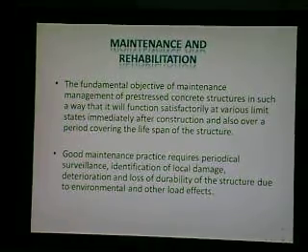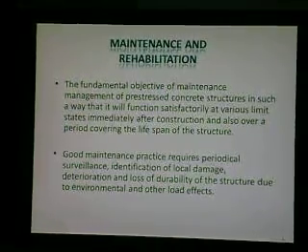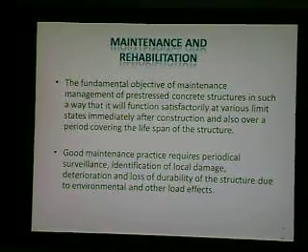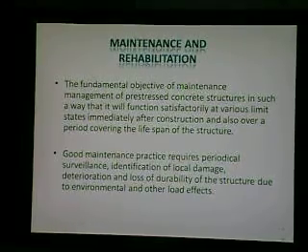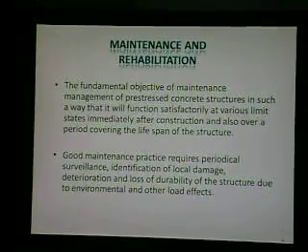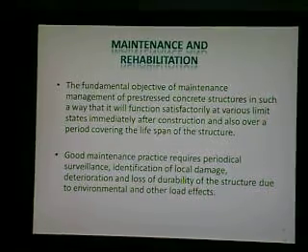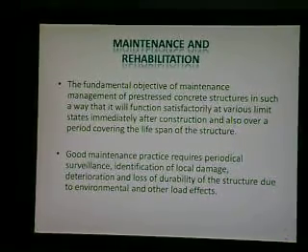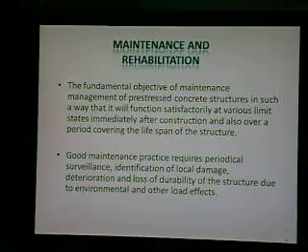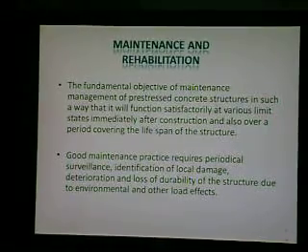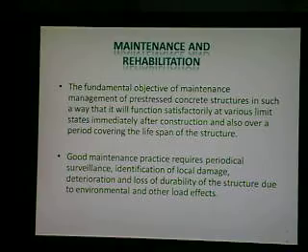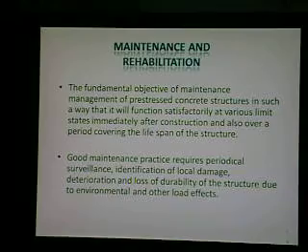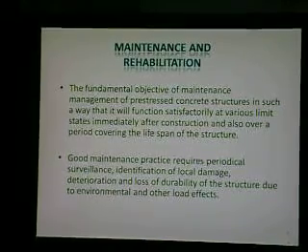Maintenance and rehabilitation. Just like post-tension slabs are an advanced technique, it requires maintenance and rehabilitation also. One of the primary reasons being it's much different from the traditional reinforced concrete construction method. The fundamental objective of maintenance management of pre-stressed concrete structures is that it will function satisfactorily at various limit states, maybe the ultimate limit state or the serviceability limit state, immediately after construction and also over a period covering the lifespan of the structure.